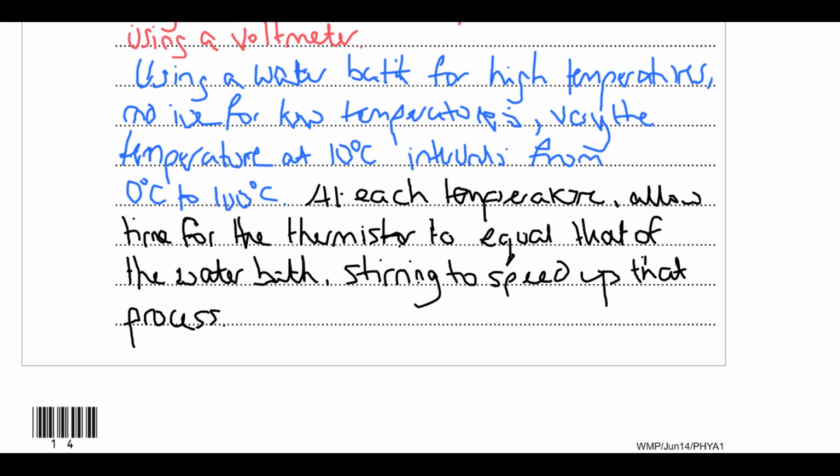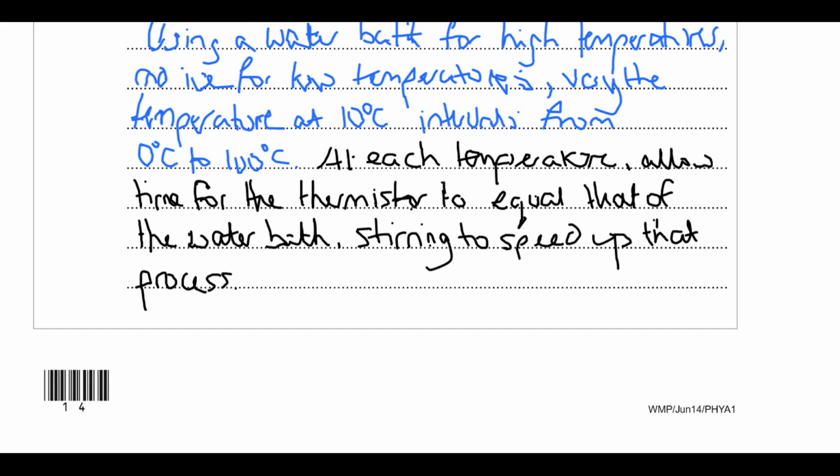So then next part, why have we got an external resistor? To keep the current low, to stop the thermistor heating up by itself.